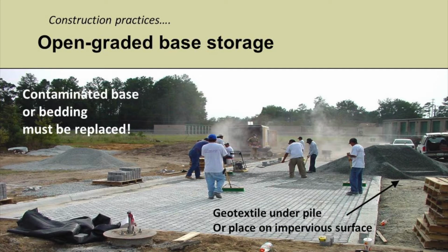You can use geotextile on the site. It makes a great cover for putting underneath aggregates. Permeable aggregates are more expensive. Open graded aggregates, washed aggregates are typically more expensive than regular dense graded road base. So your contractor is not going to want to have a pile of that and not use every bit of that that's available on the site.